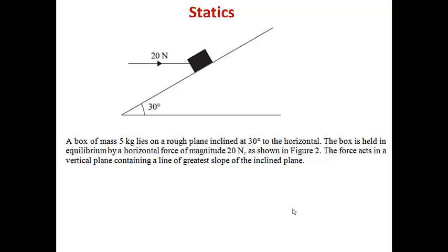What forces do we have? Firstly, we know the mass and therefore the weight of the particle. We know there's a reaction normal to the plane. Finally, we need to add friction. The question that one has to ask is, will the friction act up the plane or down the plane? With the information given, there's no way of telling.